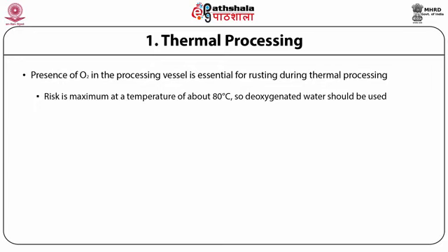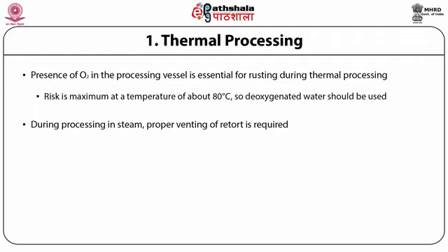Therefore, when full boiling is not required, the water should be deoxygenated and preferably treated with corrosion restrainers. When cans are processed in steam, it is important that proper venting of the retort occurs so that all the oxygen initially present is driven off from the retort by the steam, as well as minimizing any external corrosion.